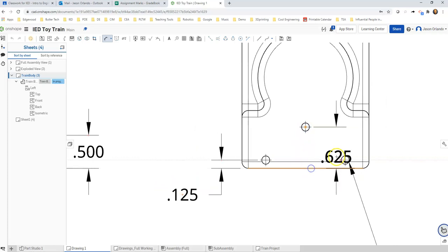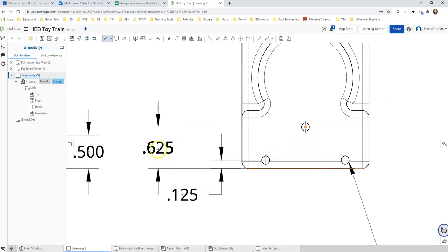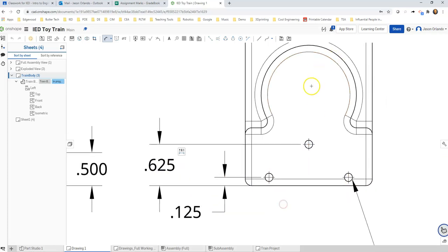I'm gonna leave the other one off and let people assume, and understand they're the same. I need the height of that. I need a center mark. I need to locate the center of this cylindrical feature. I'm going to do that from the bottom.